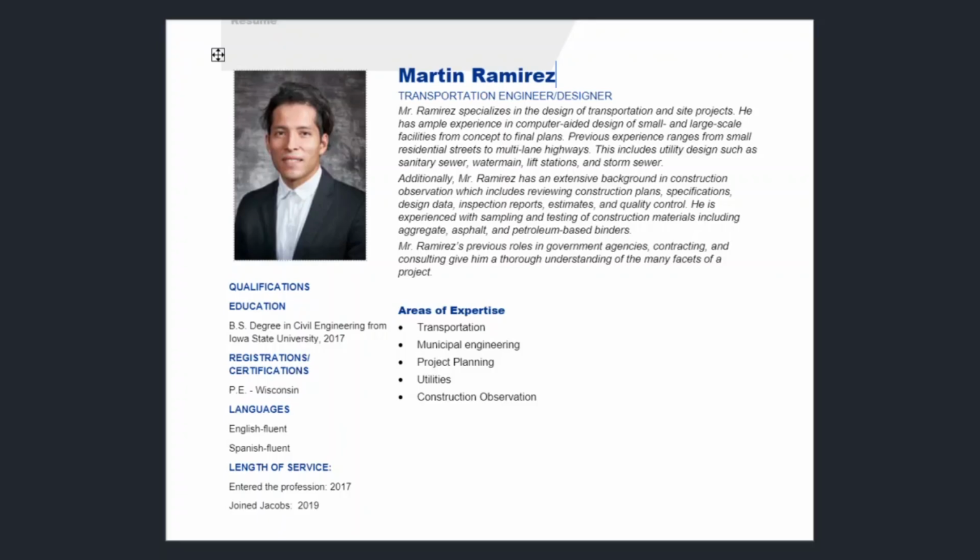However, it was a combination of projects in Nevada that led me to the use of Subassembly Composer, which is today's topic. The first project that introduced me to the need for Subassembly Composer was one in which I was using InRoads, and I got to see how modeling was done there. I found it very interesting how you create what Civil 3D calls subassemblies over there. It was done visually in a very graphical way that was technically coding, but it just never felt like you were coding anything.